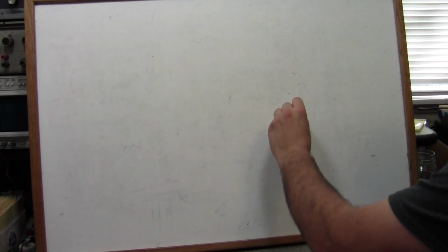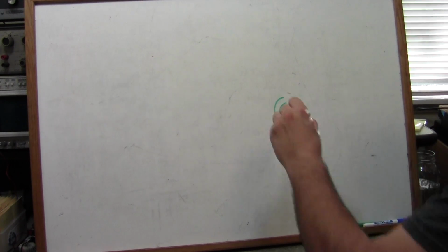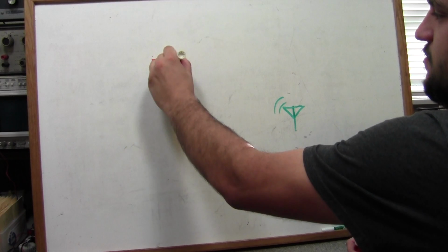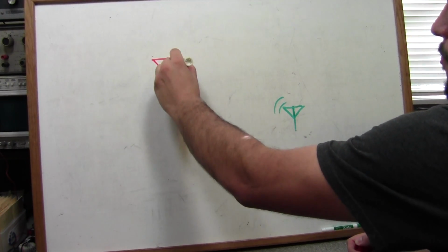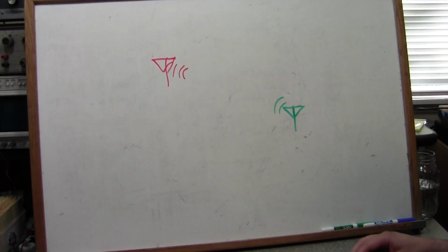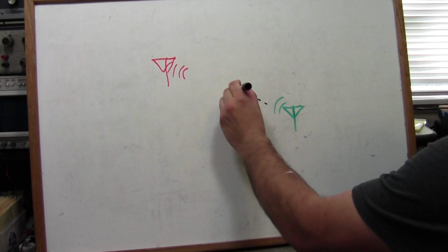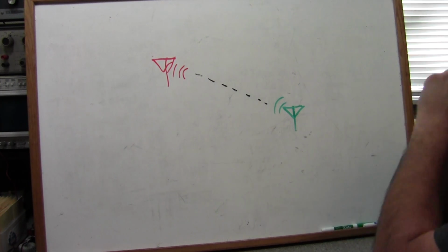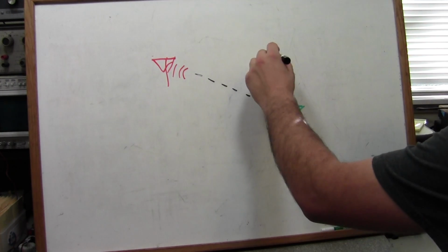How selective fading happens is that if you have one station that's transmitting, like this, and you have a single antenna that is listening for it over here, ideally, the radio signal goes straight there. Unfortunately, this would require line of sight from everything to everything, and the Earth is convex and not concave, which is rather inconvenient and makes this non-feasible.